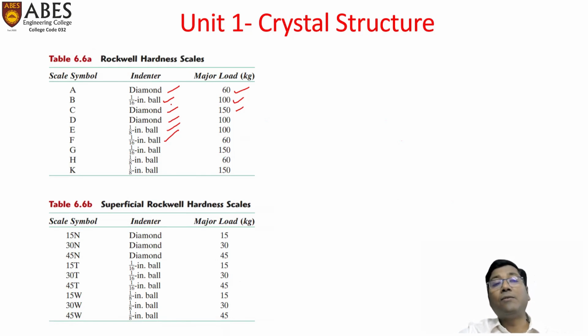Just mentioning the Rockwell scale clarifies what the indenter is, what the size of the indenter is, and what major load category was applied for that indentation.